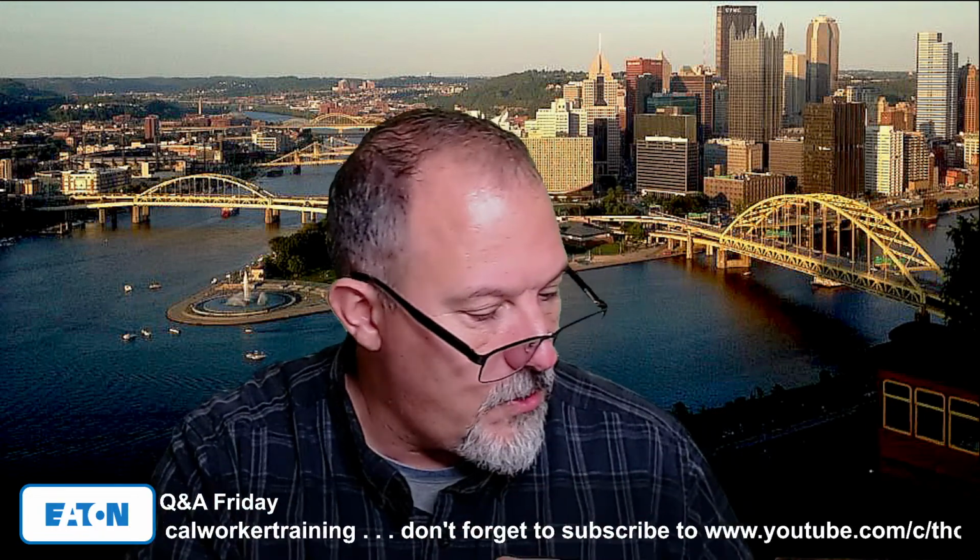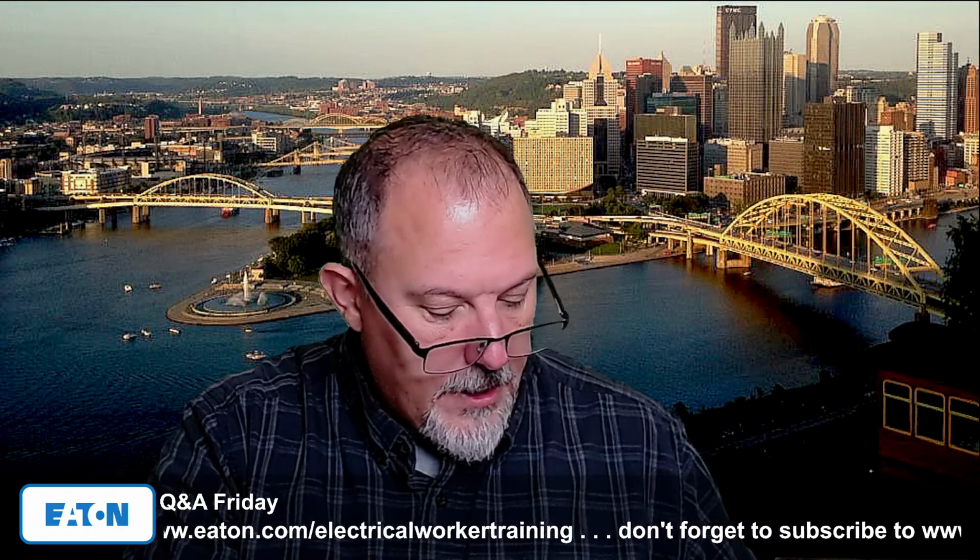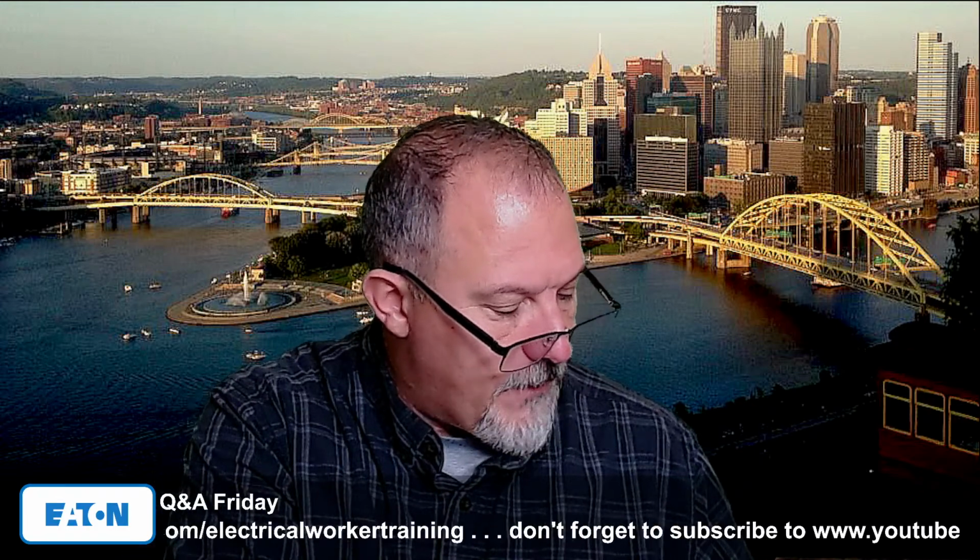Back over to the question. On the Chapter 9, Table 9 question, in addition to the insulation versus uncoated wiring thing, and remember, this was a question that came up during that Q&A Friday, where the notes say, these values are based on the following constants: RHH wires with Class B stranding in cradle configuration, where conductivities are 100% IACS copper.